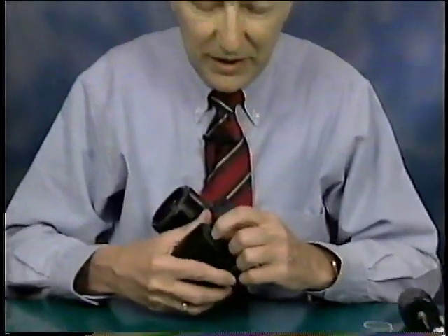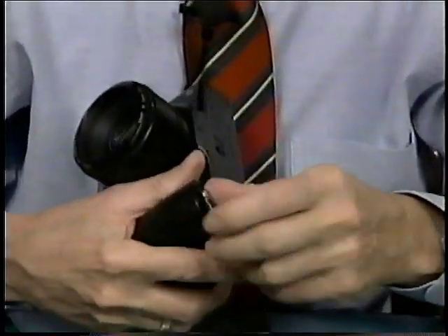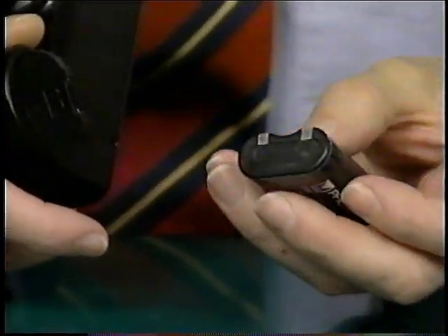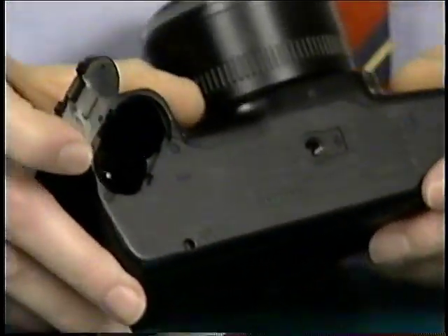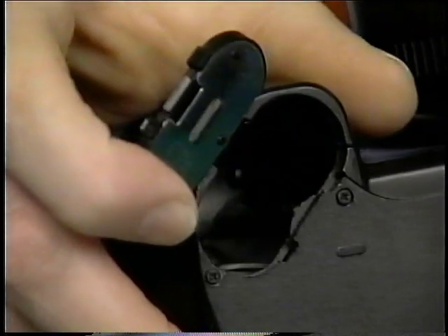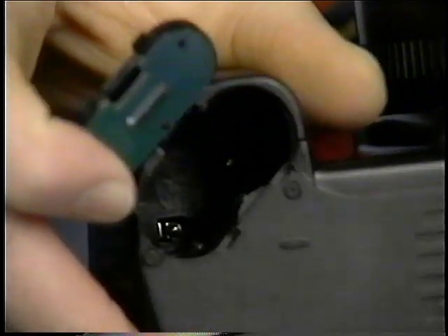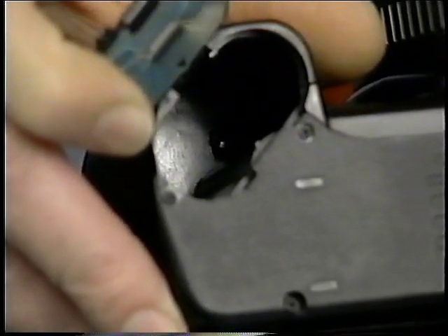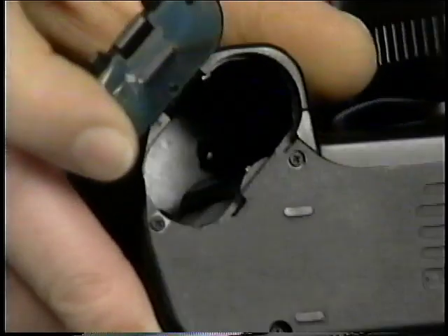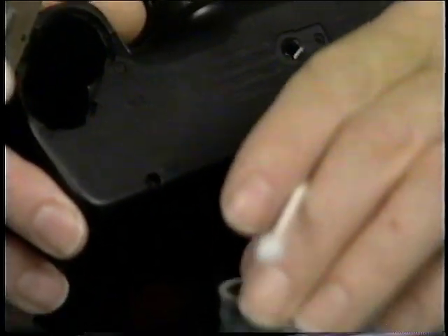Next, you'll want to look at the battery contacts, and in this camera, this particular camera uses a 2CR5 lithium battery. The battery contacts then will be quite high up inside the compartment. You notice most of them are nowadays stainless steel, so they don't tend to corrode so much, but they will sometimes get a little bit of dirt or a film on them that prevents good battery contact, and you can get erratic operation. So again, we can clean those using a cotton swab.